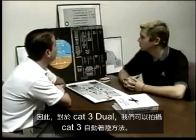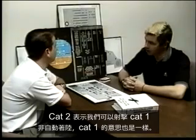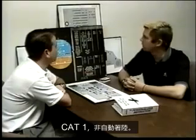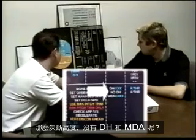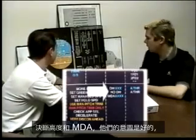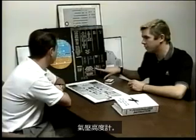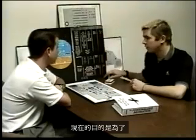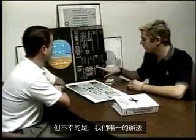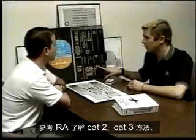Cat 3 dual, we can shoot a Cat 3 autoland approach. Cat 3 single, we can shoot a Cat 2 autoland approach. Cat 2 means we can shoot a Cat 1 non-autoland, and Cat 1 means the same thing. What about the decision height, no DH, and MDA? Decision height and MDA, they had good intentions, but decision height truly means radio altimeter, and MDA means barometric altimeter. Now, the intention was that these were going to be for all the decision height approaches, but unfortunately, the only approaches we reference an RA on are the Cat 2, Cat 3 approaches.